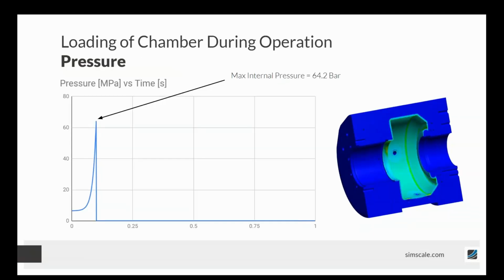So the same goes for the pressure. This was measured in experiments. We can apply that internal pressure on the surfaces internal of the combustion chamber. For the purposes of explanation, I'm going to call these the application surfaces. I refer to them quite a lot in the simulation.